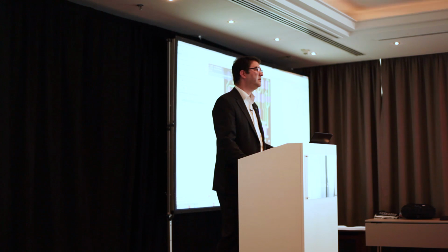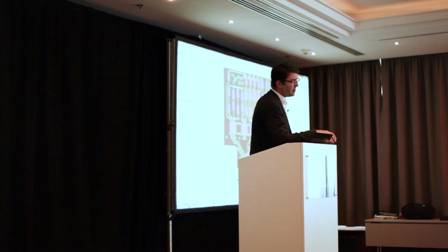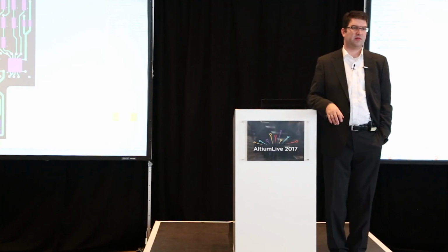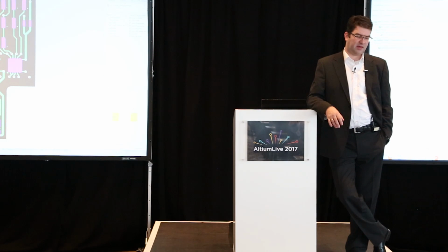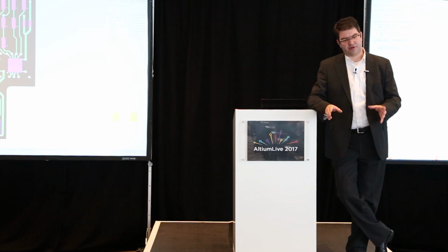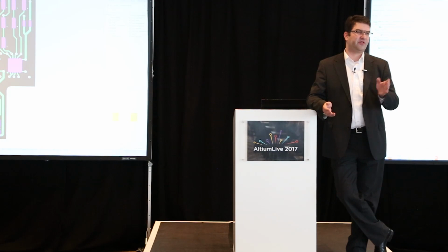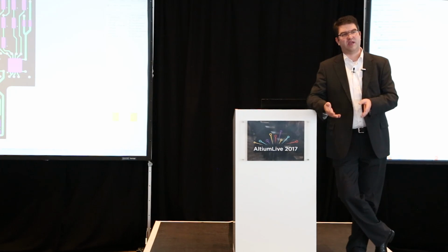How good are the vendors' step files? Are the step files good enough to verify, particularly during the design phase, for collisions? Or these step files, because I assume they are always showing the nominal values? Yeah. They always show the nominal values, which is, for some components, not easy for us. Yes, that's true. And this is something the designer or the guy who's making the library really needs to take care of, that we have the maximum information in the BOM. So that there are additional parameters, X, Y, Z, plus the tolerances, so that we can work with that one.